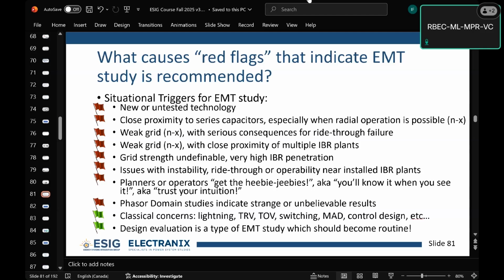And at the end of the day, the real system is going to have differences that might cause you to be out. The other little things, like compiler differences, are common, but they're kind of anomalous. You already know that there's something wrong. As soon as you're getting different results from different computers or different compilers, or sensitivities to network equivalence and things like that, you already have a sense that there's a problem or a sensitivity in your study process that should give you pause. You need to sort that out and figure out how to add confidence in that area before you continue on. Other than that, you're adding disclaimers back into your report that say it might be wrong.